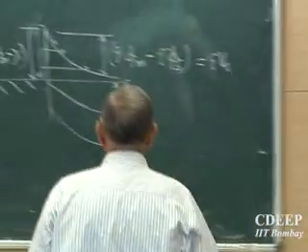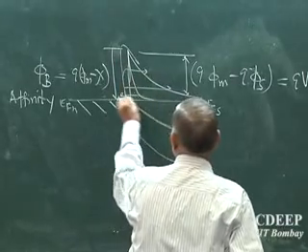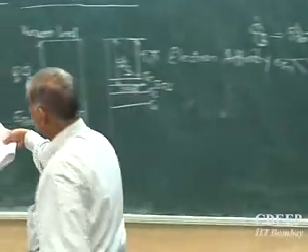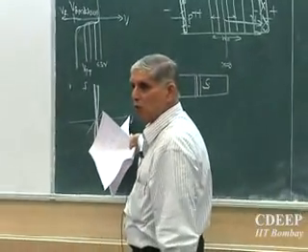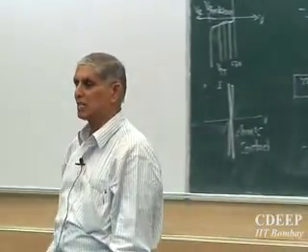Is that correct? So if you have a metal-semiconductor contact with a heavily doped semiconductor, most of the carriers can go like this. So which is the equivalent case here? Ohmic contact. If a metal-semiconductor contact is to have a large tunneling current both forward and reverse, then you should have a heavily doped semiconductor with metal connected to it. But if it is lightly doped, it will create a barrier, and if it creates a barrier like a PN junction, it can have forward bias and reverse bias currents.